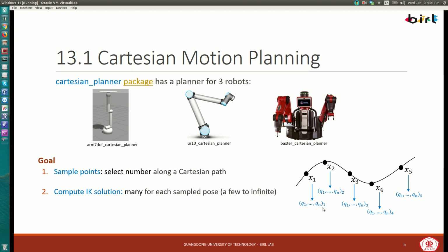So imagine the robot is carrying a cup, and so your wrist or your tool is either pointing up or pointing down. So that the two orientation axes are set. The way you hold the cup will fix, say, the y-axis of rotation and might also fix the x-axis of rotation. But there's one axis that is free to rotate in any direction. That'd be the z-axis of rotation with respect to the tool.